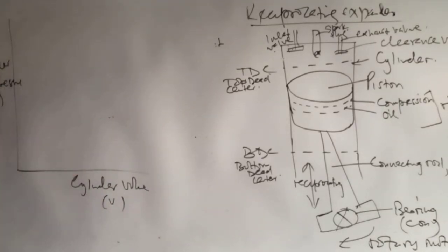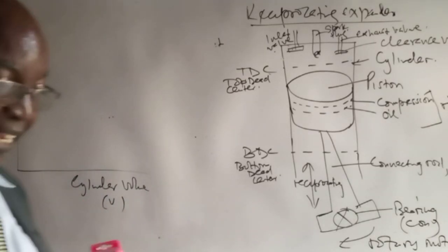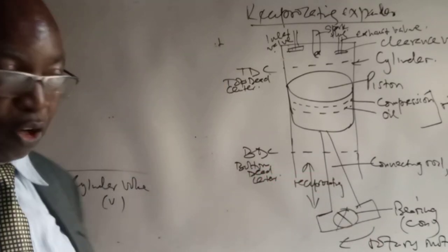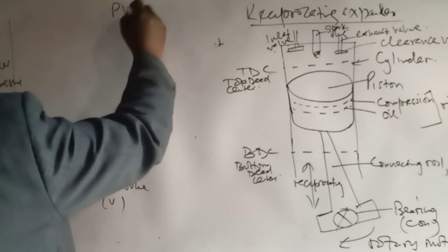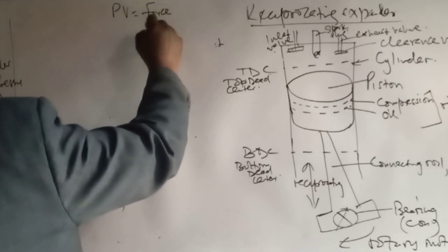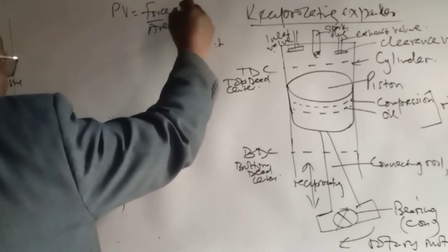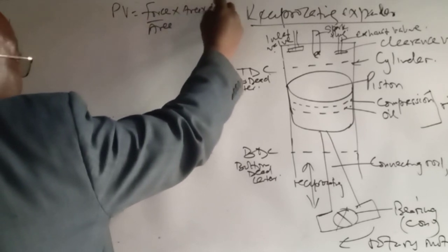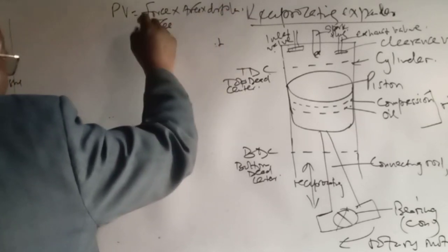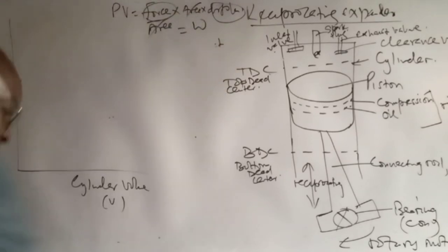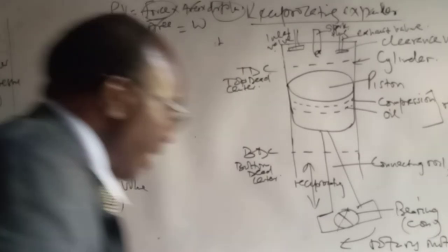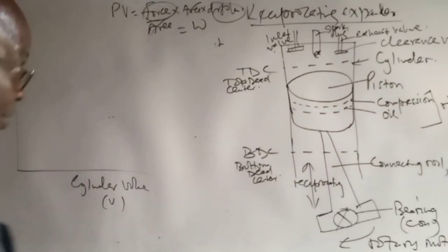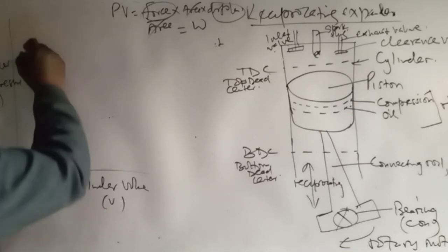And remember, this is an indicator diagram, and it's a graphical representation of the total work done in that particular system, because if you take pressure volume, pressure is force over area. Remember, volume is area times some displacement. So if area cancels, you have force times displacement, that will give you work. So the area under those plots is normally representative of work. So the kind of profile you get for that rotary reciprocating expander, we will get